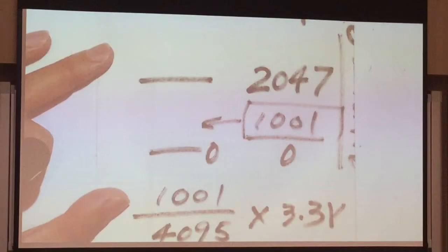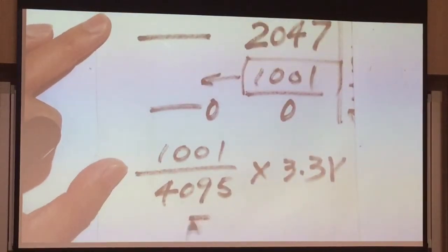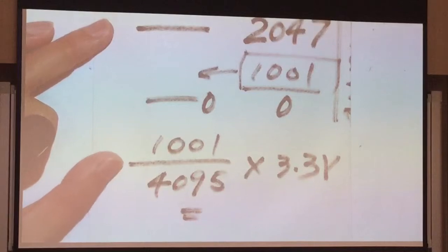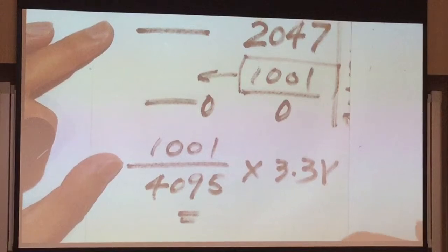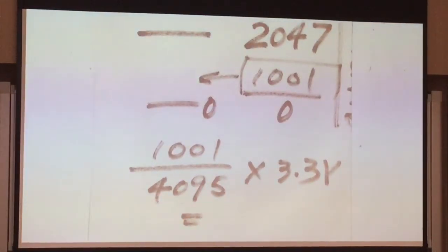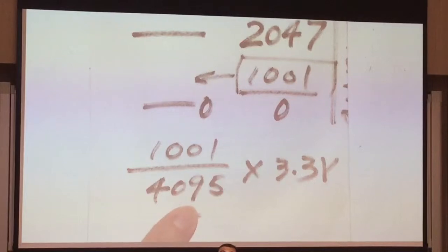That will give you the actual voltage value. So it's like a scaling. The analogRead function does not give you the actual voltage value. Any questions? You can even check whether it's 4096 or 4095.